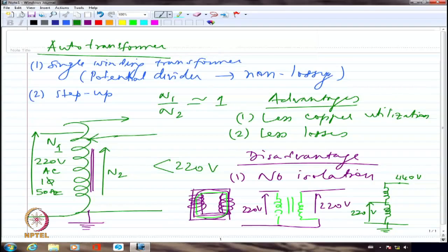Nothing more than that. Or 220 times root 2 at the most, because the peak of the voltage is root 2 times 220. But in this particular case, what is happening is, the voltage at this point happens to be at 440 volts. So the insulations can rupture if I continue to use it for too long a period, because it is facing the brunt of that 440 multiplied by root 2. That is the voltage that it is facing on a continuous basis.